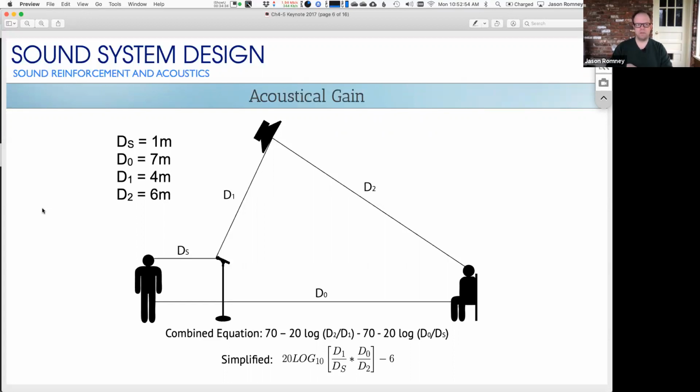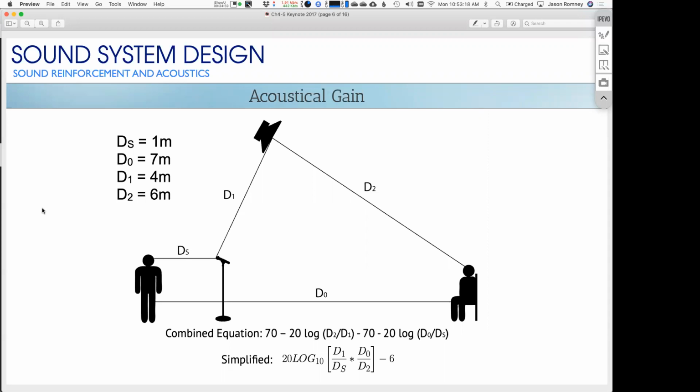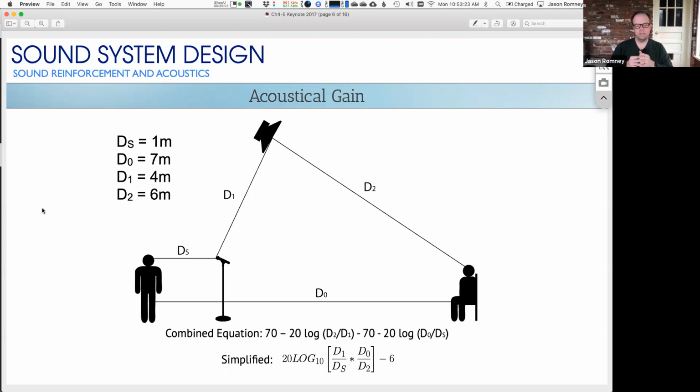And the only time I've ever been able to do vocal monitoring like that is if I've got a boom mic coming right here in front of their mouth, especially if that's a directional boom mic. Then you can usually get away with the vocal foldback without too much trouble. So it could be that was the other problem, is maybe you had vocal foldback on stage. Yeah, a lot of what he was doing was on the near fields and stuff that were causing a lot of problems. Yeah, so, again, you're going to obliterate the frequency response.